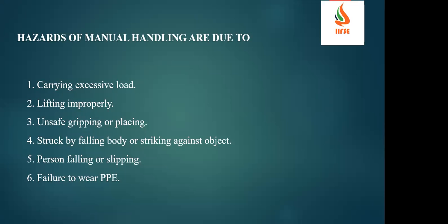Maybe the shape is very round, maybe the size is very big, even though it is less weight. And maybe some of the materials are very delicate, or of irregular shape, so it is difficult to judge the center of gravity, so that leads to lifting improperly. And unsafe gripping and placing: he is not having the proper grip, but he is lifting the job. That is also one of the hazards.